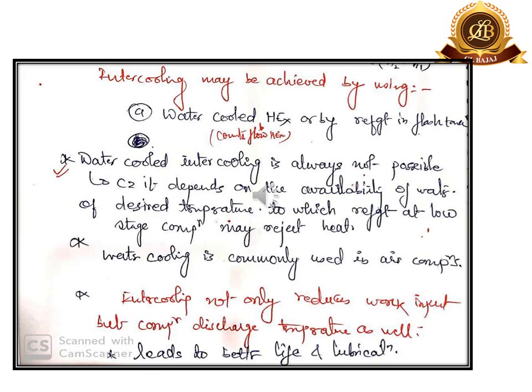Now, water cooling is commonly used for the air compressors only. Intercooling not only reduces the work input but also the compressor discharge temperature is further reduced. So, it leads to better life and lubrication of the compressor.